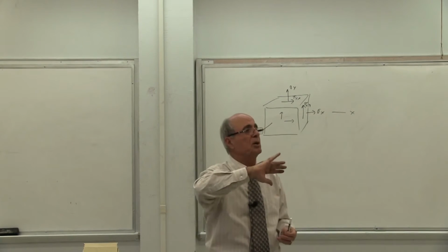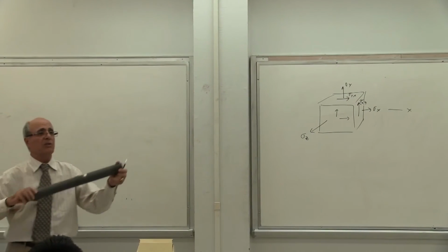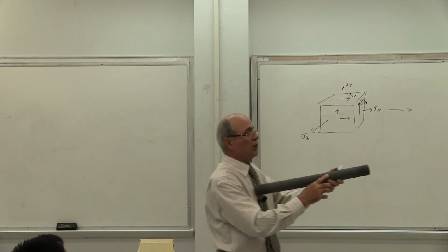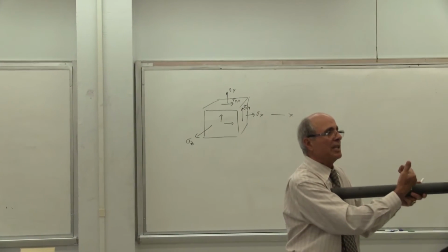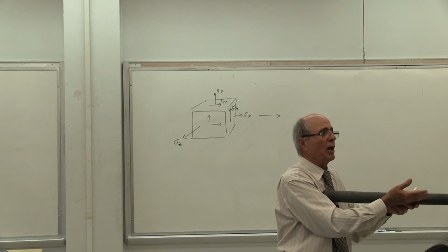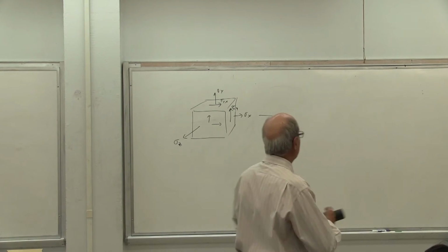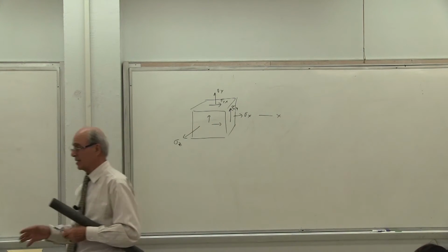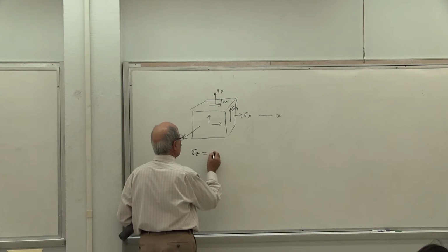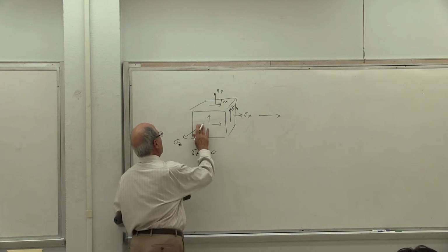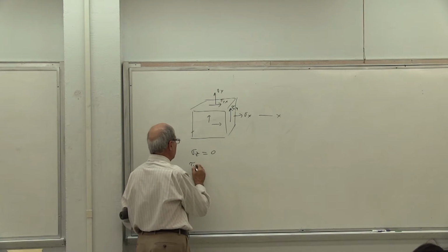So look what happened there, guys. If I multiply here by 2 and divide that by 2, the format becomes exactly this format, yes or no? And since this later on became a Mohr circle, yes or no? That also becomes a Mohr circle, except with one difference. Sigma x becomes epsilon x, sigma y becomes epsilon y, but instead of tau, I have to use gamma over 2. So write it down. That's the only difference between the Mohr circle for a strain and the Mohr circle for a stress. Everything else is parallel, exactly the same.